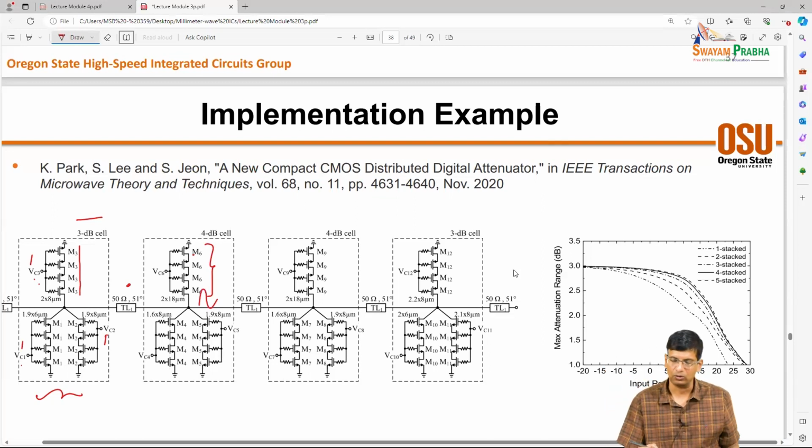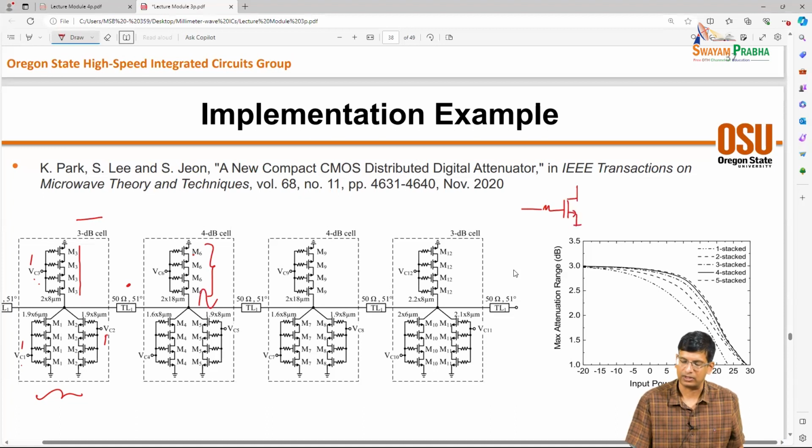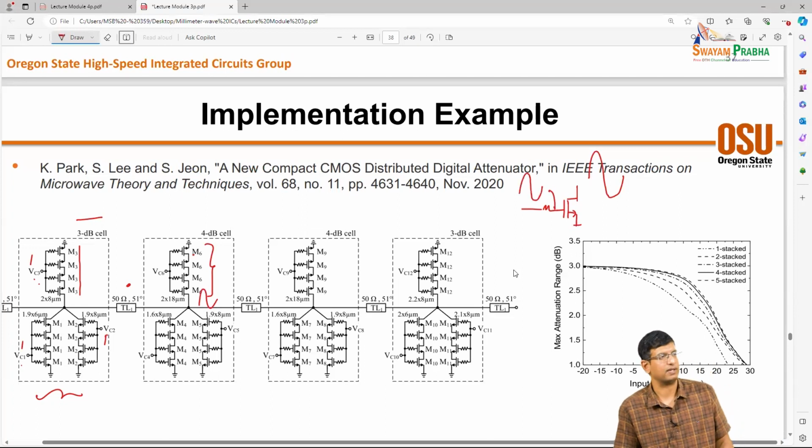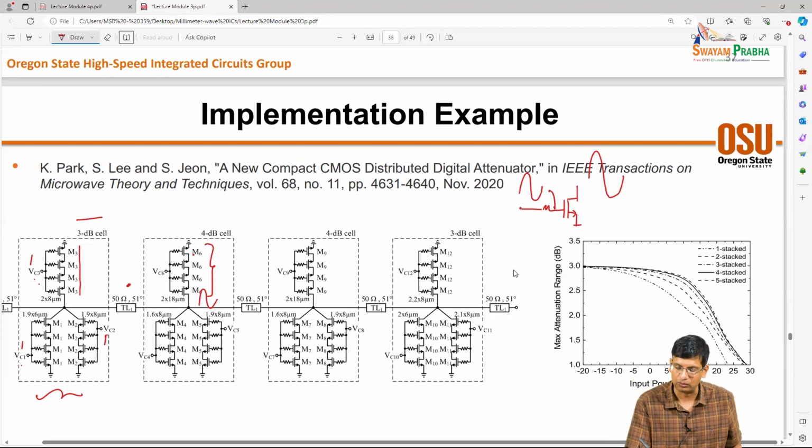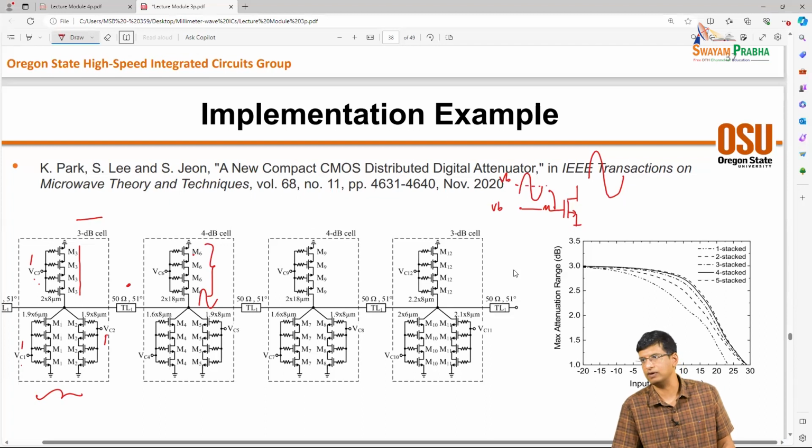So we can do some things like float that switch control voltage, right? So then as this swing goes up and down, this gate swing also moves up and down along with it, right? And what we then do is bias this gate up, right? So then this is not moving about 0, this is moving about VB, right? The gate is moving about VB.